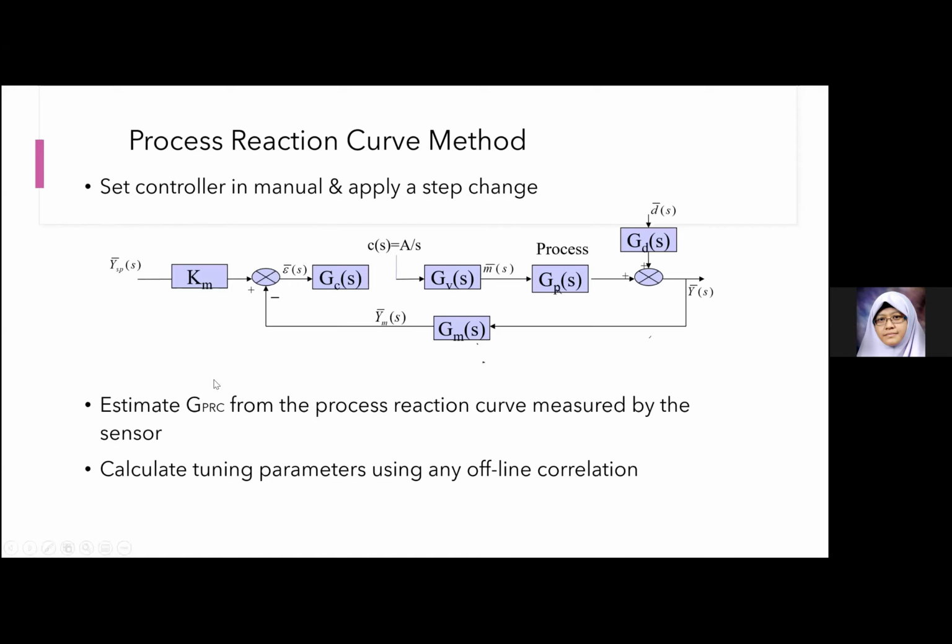Now, if you want to do this in real life, when you do the lab or when you're in the plant, normally the offline method is not that favored because you have to take the system offline. When we say we take the system offline, it means that you turn off the controller. There's a switch; you don't pull out any wire. You turn off automatic control, go to manual control, and from manual control, you can manually change the input to the valve.